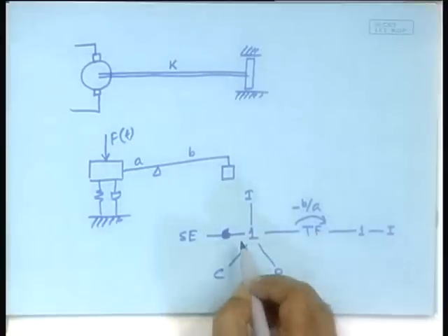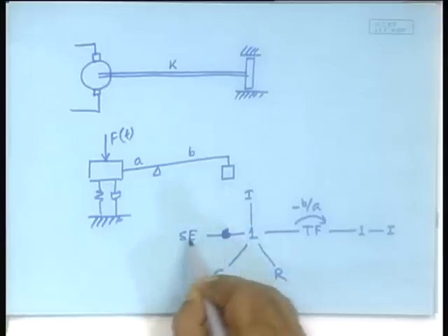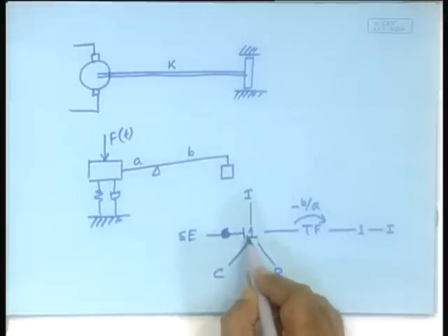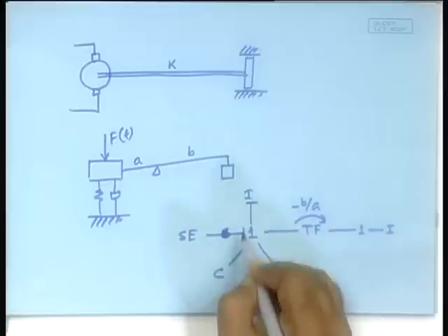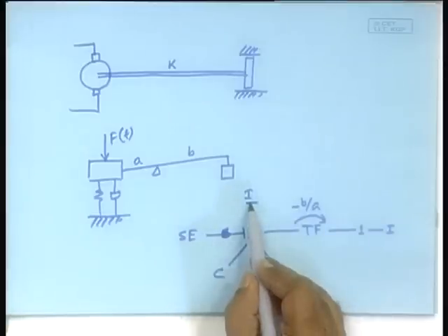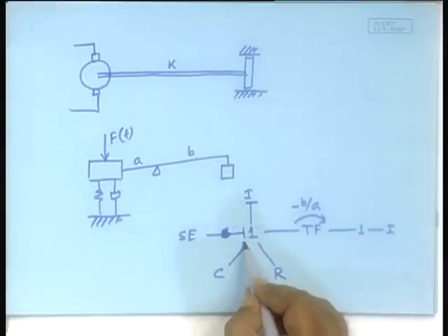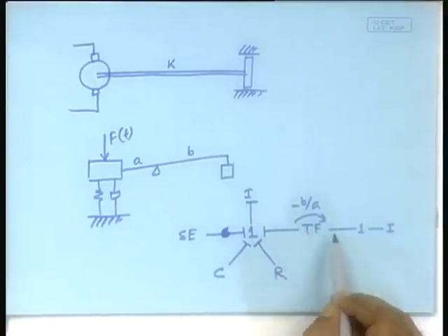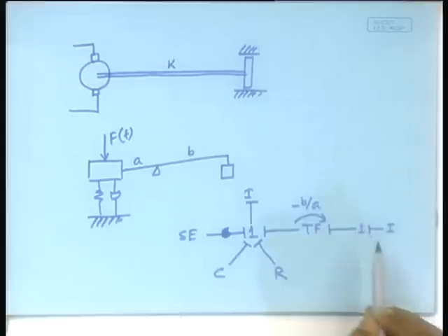In that case you would notice, let us just do this once again to refresh our memory how the differential causality comes. Suppose we start from here, the C element receives flow and gives effort. Now, this one junction, this will be integrally causal. So, this brings in the flow information, the other ones must distribute the flow information. A transformer has received the flow information, therefore, it must give out. One junction has received the flow information, therefore, it must give out. Now, here we find that this is not properly causal, differentially causal, because it is receiving the flow information.